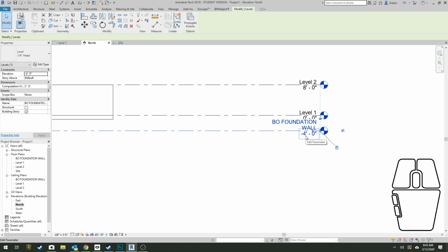So it is 4 feet below the frost depth of this area. So can I feel pretty confident putting the bottom of my foundation wall at 4 feet? Okay. I need to consider that. It's something I have to think of, but I feel pretty confident with this, so I'm okay with the foundation being at 4 feet. I could put it higher than that based on my frost depth, but because of how I'm creating my crawl space, I don't want to put it higher than that. I want it at 4 feet. So you put this where you want to put it based on what you're creating.